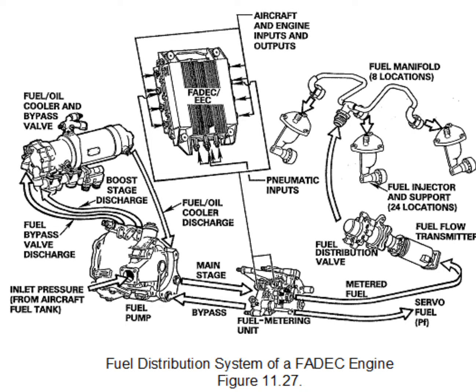When should a turbine engine be trimmed? Loss in engine power, manufacturer specifies. What specifications are used to trim a turbine engine? Data plate on the engine.